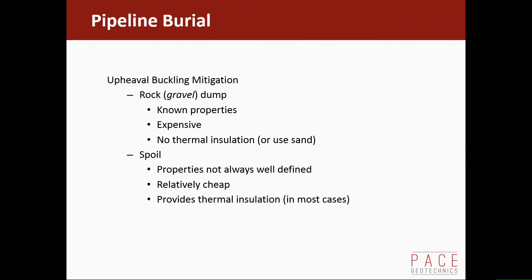You can use sand, but it's not ideal using sand. It's much more expensive to actually purchase because they're not set up to load sand into a vessel in the same way that they are set up to load rock into a vessel. And also because you're putting it down at a fall pipe vessel, which I'll show later, you've more chance of sand being lost, so you've got a higher wastage.